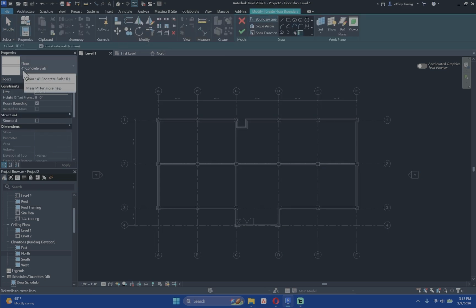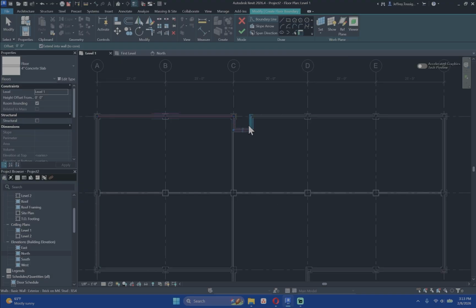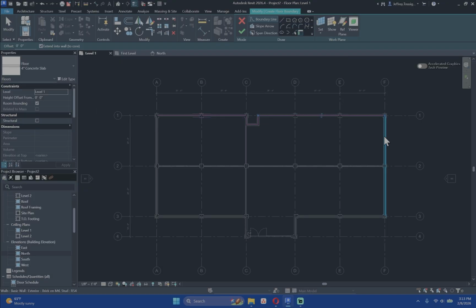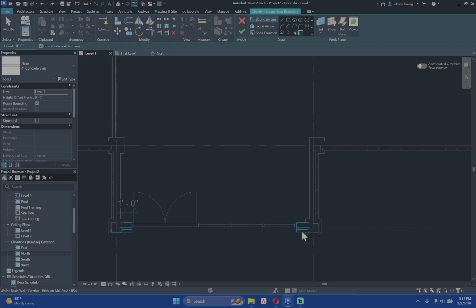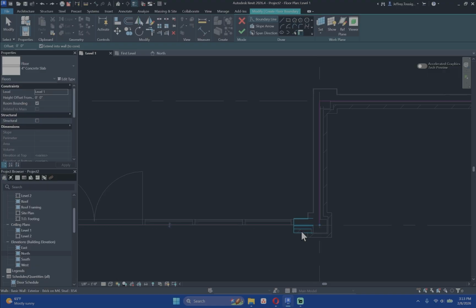We're going to use just the 4-inch concrete. Again, if that changes, we just change its thickness and it'll update for us. And also, as I said, with the pick wall tool going, when we go around and pick our exterior walls, if we decide that these aren't supposed to be the locations of the exterior walls, that's why we are not using, oh, I'm going to make sure to pick the wall, not the curtain wall.